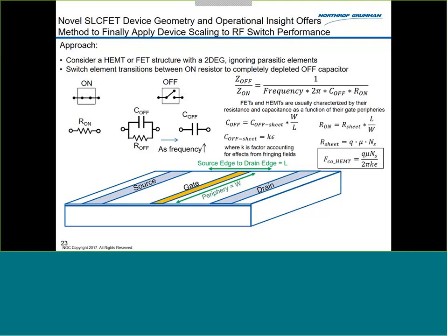The reason, I think, is actually quite simple in that it goes to that fringing field and that dielectric constant. If you look at high performance silicon-based switches, they're all SOI devices, and there you're trading your dielectric constant for an oxide, so a 3.9 relative to something just under 10 for a gallium arsenide switch. So even though the carrier density and the mobility are not as good, once again it's these fringing fields. It's much better working on those to have less capacitance associated with it.